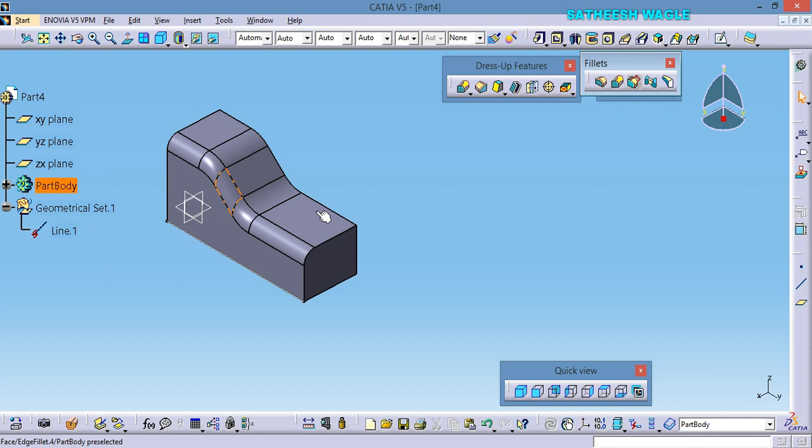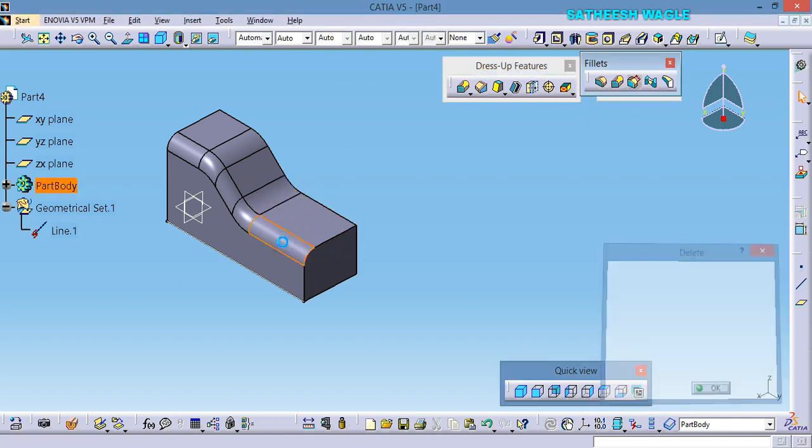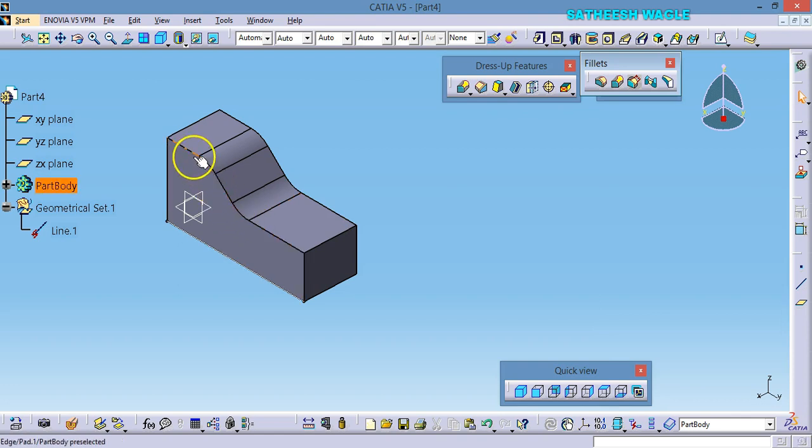So the main use of the circle fillet is when sometimes there may be times when you need to fillet consecutive edges with no tangent continuity. For example here we have some tangent continuity, see here, this edge has tangent continuity. But sometimes there will not be tangent continuity here. At that time, you want to treat it as a single edge logically.